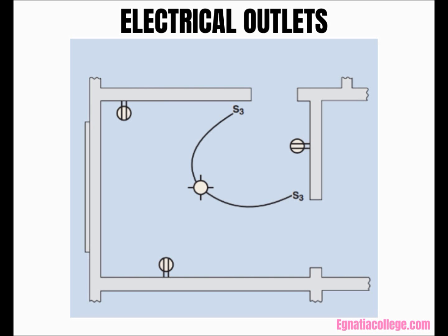Each type of outlet is represented on the plans as a symbol. This figure shows the outlets by the symbol as a circle with 2 horizontal lines. The curved lines in the figure run from the outlet to the switch or switches that control the outlet. These lines are usually curved, so that they cannot be mistaken for hidden edge lines. Outlets shown on the plan without curved lines are independent and have no switch control.